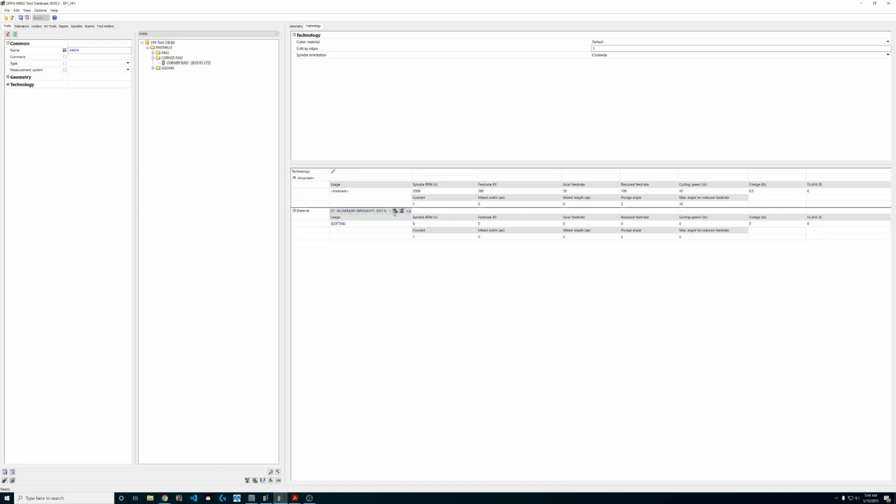Hey, look at that. Raw aluminum has appeared. Now, just like we've said before, if we had 50 different materials defined, we'd have a drop-down menu with all those materials. Now we're starting to see how this whole system is coming together. Where this is super robust is having drills that are suitable for 10 different materials. We can take that drill, apply all these different materials to it, and put in the appropriate data for those materials, and every time we are working inside hyperMILL, we can grab that tool and have this good feed and speed data and increase that whole process reliability and error proofing. It gets really, really good.